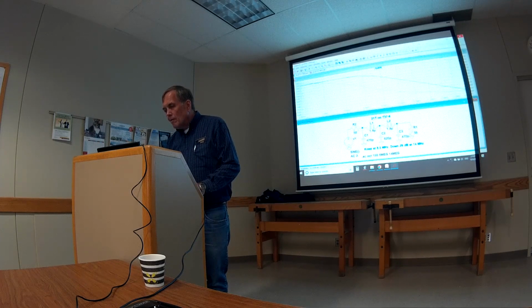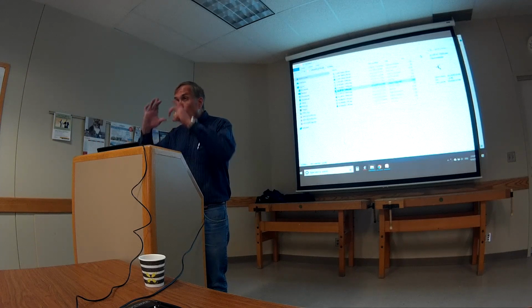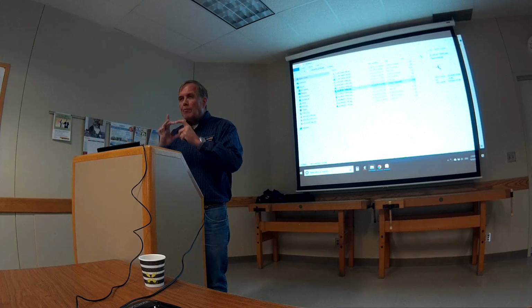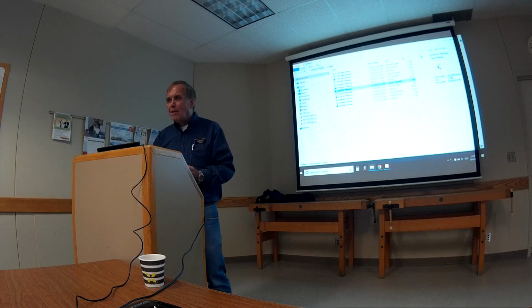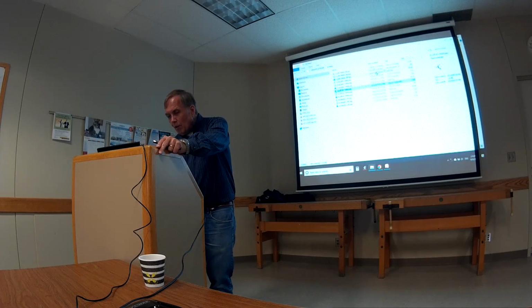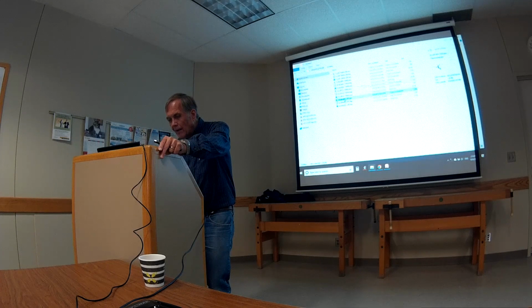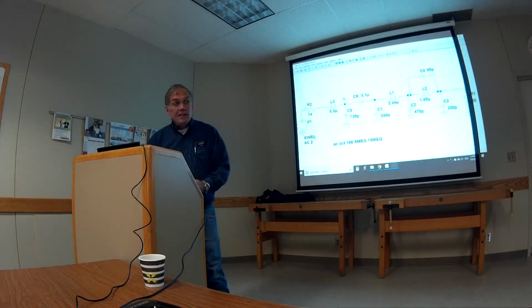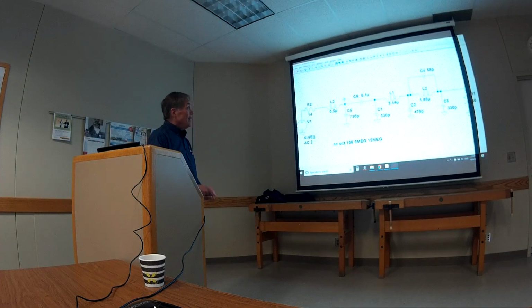Now I'll show you one that I just made for that little rig. I was showing you the little 5-watt rig. By the way, I got that putting out 5 watts now, 5.2 watts by tweaking it slightly. And here's a low-pass filter I designed for that little guy. Now this has got a special little tweak to it. It's got this little extra capacitor in here. The capacitor, I'll show you how that works. It's going to put a notch in there, right at 14 megahertz, which really brings it down.